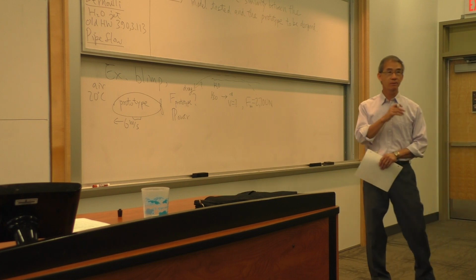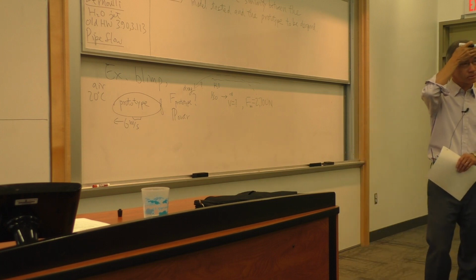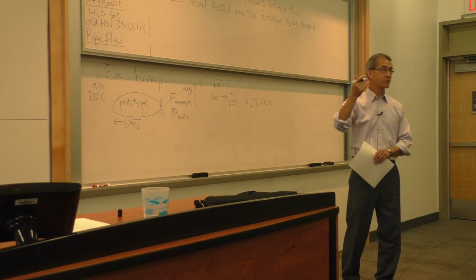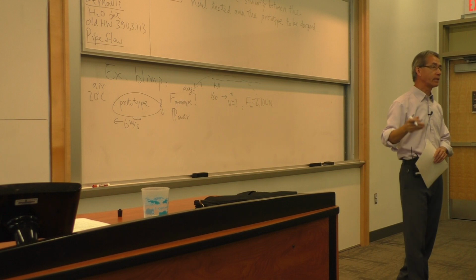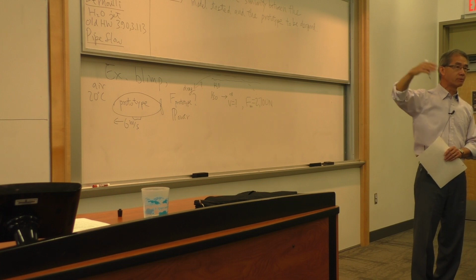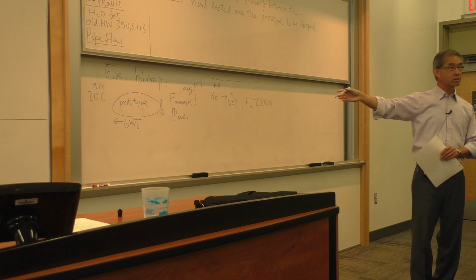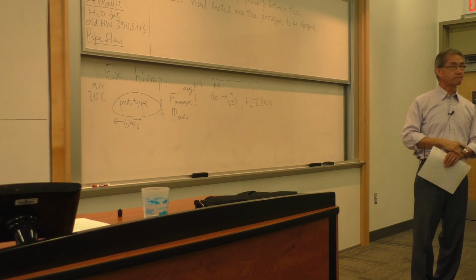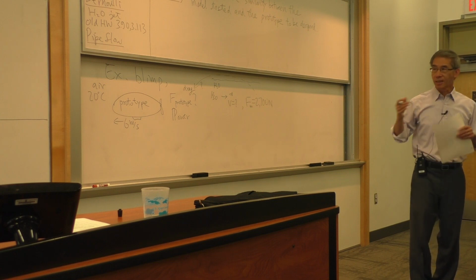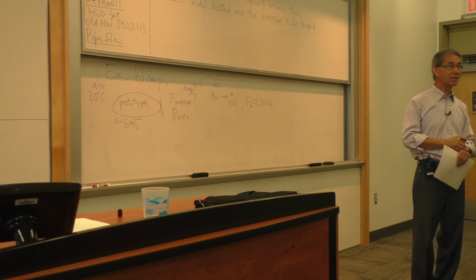Okay? Yes, there was a question about why do we still need these physical experiments when we have software simulation? Oh, that's a $1 million question. Even here, you have computers, you have something which we'll touch on called computational fluid dynamics, where you set up the entire domain with the geometry of this prototype, put it in a computer and it spits out a number, which will tell you everything you want to know in the flow field: pressure, temperature, and the drag. But it turns out those simulations make a lot of assumptions. The most important of which is assuming some type of turbulence behavior, which we haven't touched yet. We will. So bottom line, those simulations are not exactly correct either.